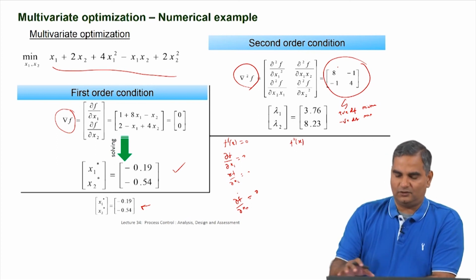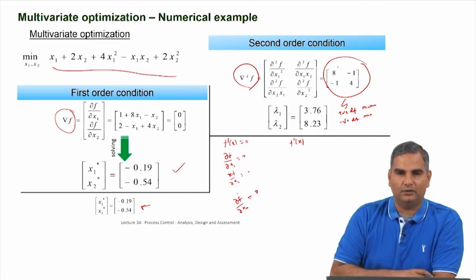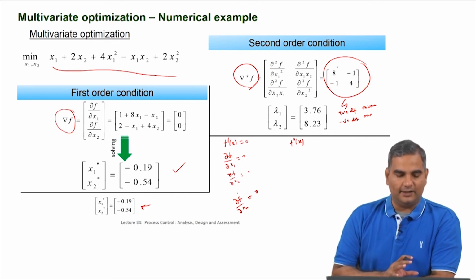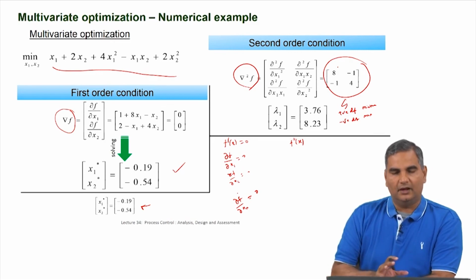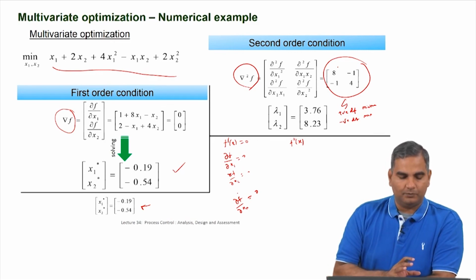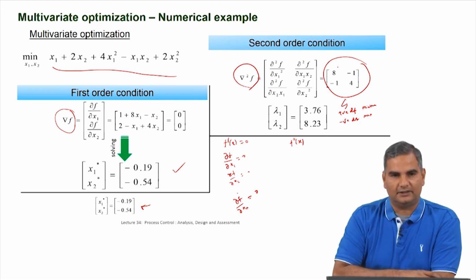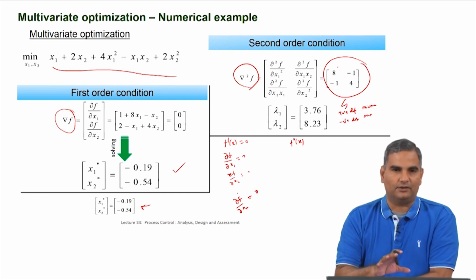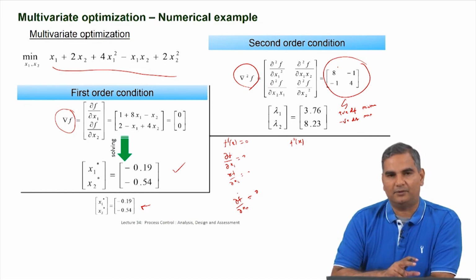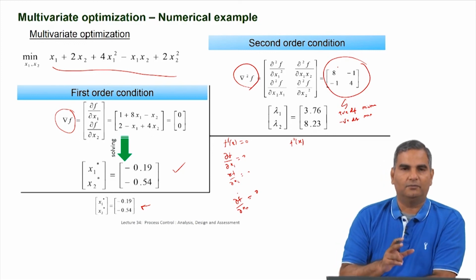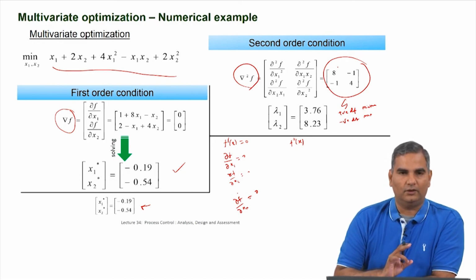So, this is just to understand that it can be done and the procedure by which software will do this, but as far as you are concerned, as far as this model predictive control portion of this course is concerned, all we need to know is that we can solve this objective function when it has multiple variables, because this is an important idea, and let me make the connection again. The reason why we are interested in multiple variables is because when I am making a move plan, I have variables u_{k+1} all the way up to u_{k+m-1}.